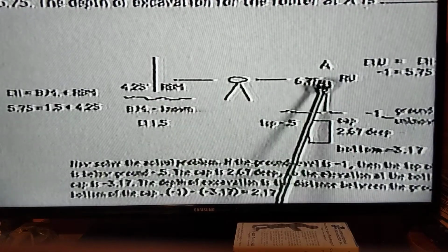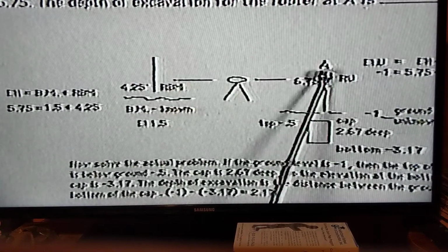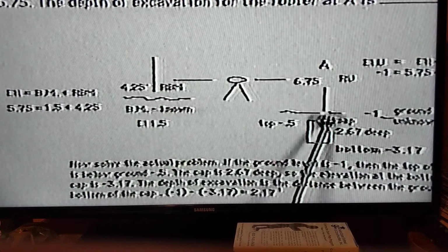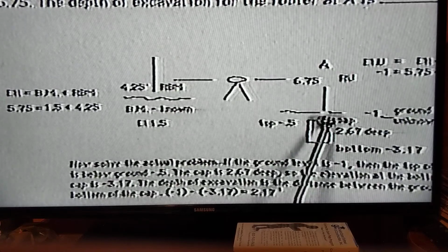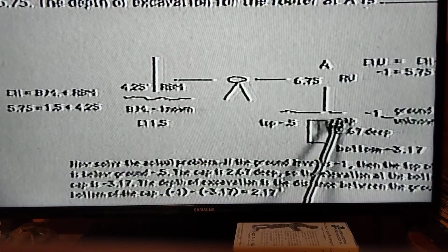If you knew the line of sight was 10, and if you knew therefore there was 5 feet distance from that known line of sight at 10 to your unknown elevation, you'd be able to figure out that the unknown elevation must be a 5. The formulas that the cram book will take you through about this do that.